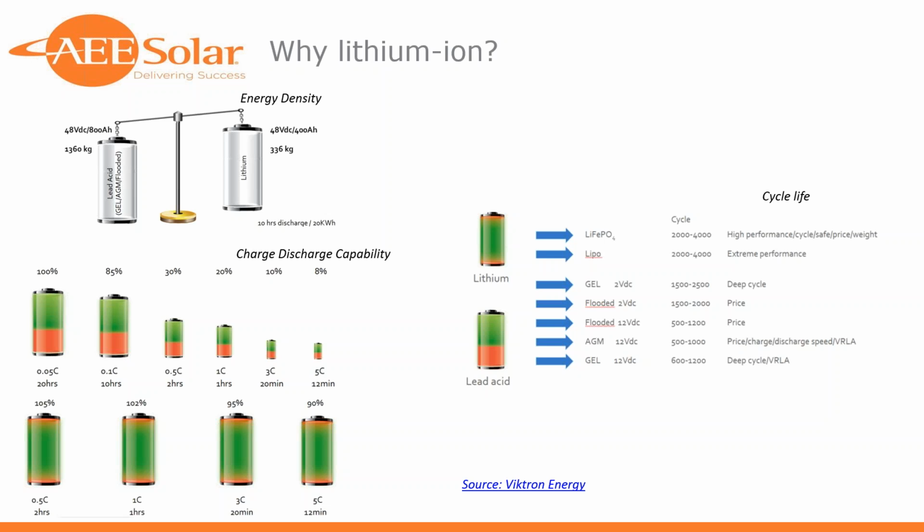Typically, we would talk about lead acid AGM chemistries in terms of hour rates. So what's the amp hour rating at a 100 hour rate? If I took this battery and discharged it over a span of 100 hours, how much usable capacity would I have? 20 hours is pretty standard for our applications, off-grid or battery backup. So at a 20-hour rate, you see there that the red proportion of that cell is basically